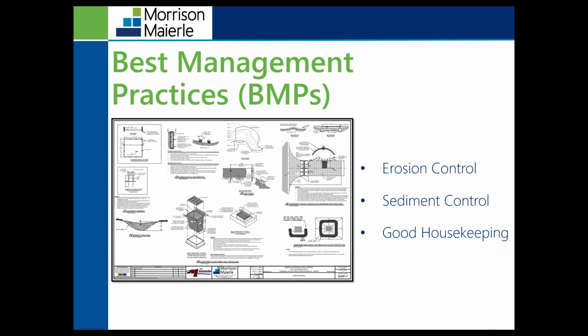So don't just place sediment control BMPs. Really use a combination of BMPs, use the erosion control BMPs at the source and then sediment control downstream, down gradient. There's also good housekeeping, waste management. Construction sites are just gonna have a lot of hazardous materials, waste materials that we're gonna try and prevent from discharging from the site. So good housekeeping practices to prevent pollutants from vehicle equipment cleaning and fueling, material stockpiles, paving and grinding operations, and soil, liquid, hazardous, and concrete waste.